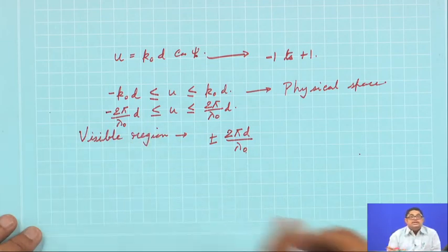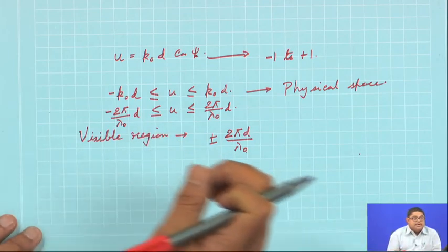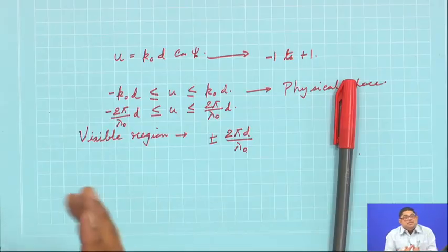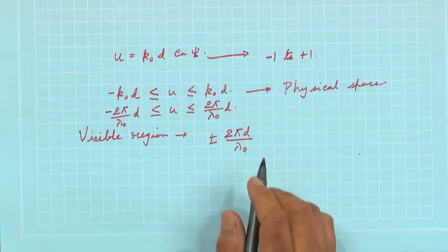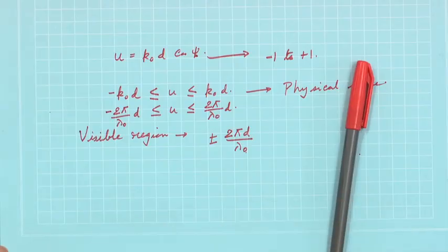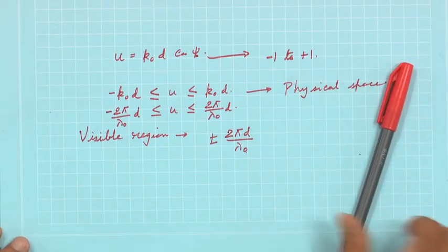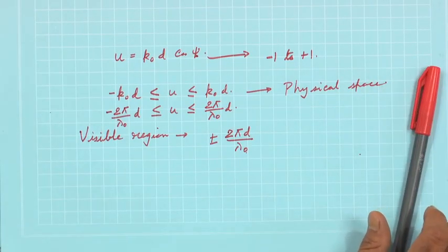So that is done by the spacing. If you make the spacing large, you can invite grating lobes into the visible zone. We will see what the requirements on d are in the next lecture.